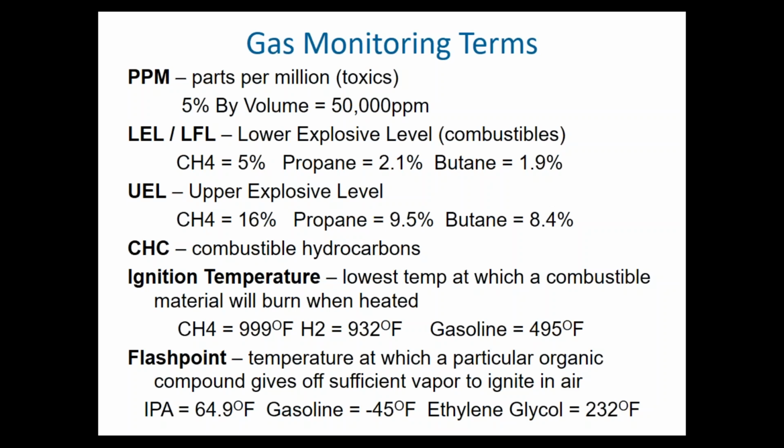What that basically means to me is that at room temperature, if you're storing this in an open vat, you really have no worry that an ignition source is going to ignite that ethylene glycol vapor, because it's just not hot enough to give off enough vapors, called the flash point. Therefore, the customer who called me really didn't need gas detection.